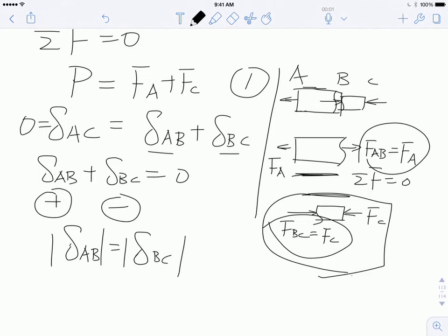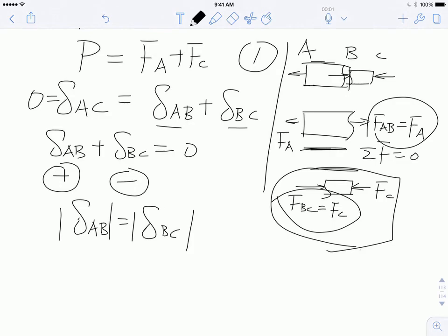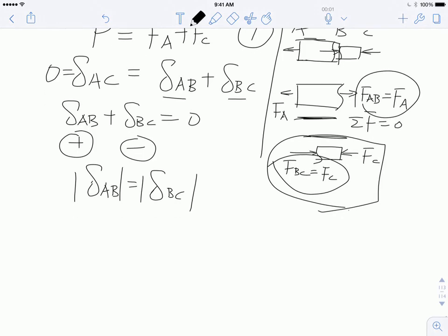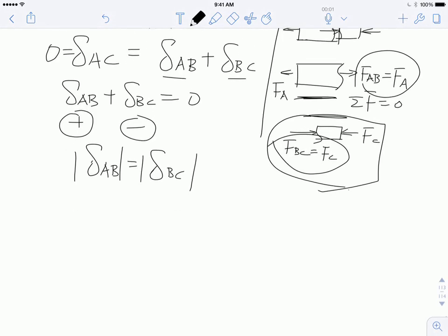Remember what I just mentioned? I really hate to deal with positive and negative signs because these are just mathematical conventions, and for us everything is physical. A positive or negative displacement means tension or compression. So I would rather just deal with the numbers, not the signs, because I know what the sign means: this means tension, this means compression. So let's do that.